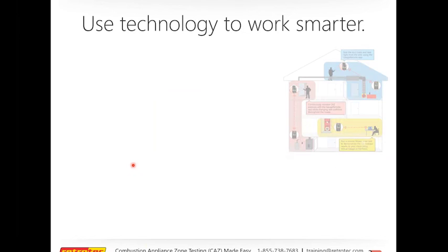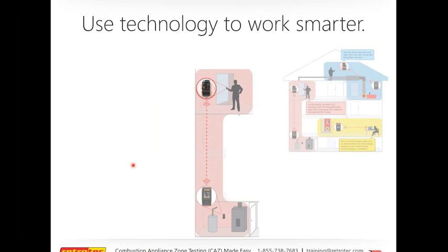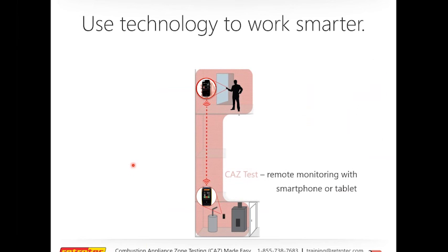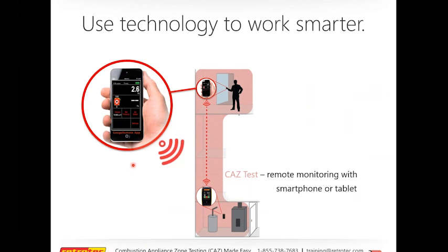So now that you've got your GaugeRemote on your phone or mobile device connected to your gauge, and if your gauge is located in the CAZ or at the blower door, as I had suggested before, no matter where you're at, looking for issues that you may have discovered, or just opening and closing doors to find out what the worst case depressurization is, you no longer have to open up a door and then walk down the stairs to look at your gauge and say, yep, that's worst case, or nope, that's not, I've got to go back up and close that door.